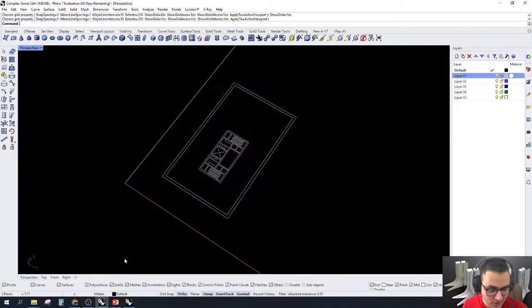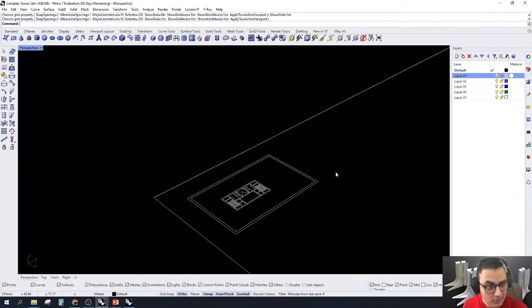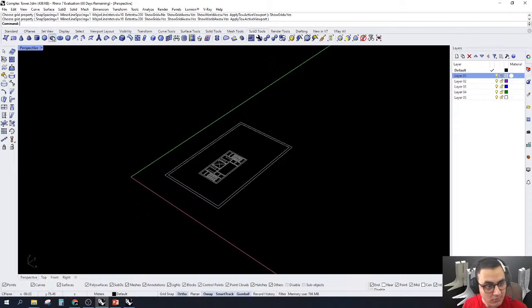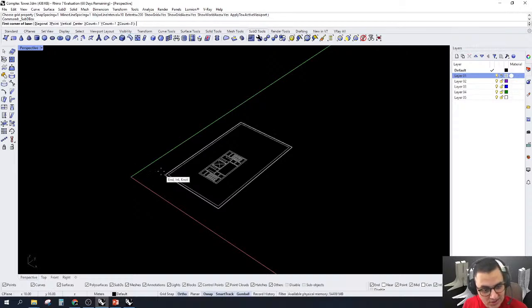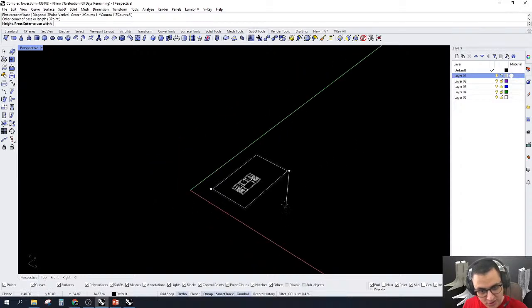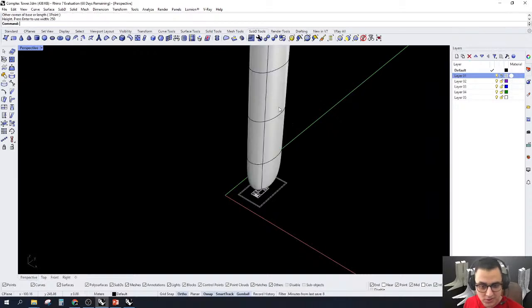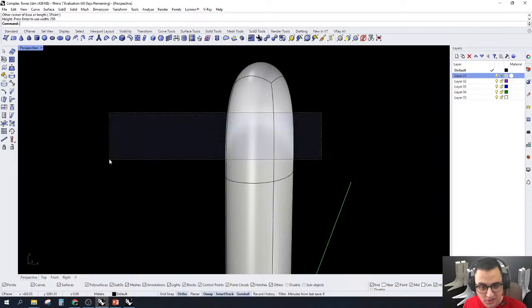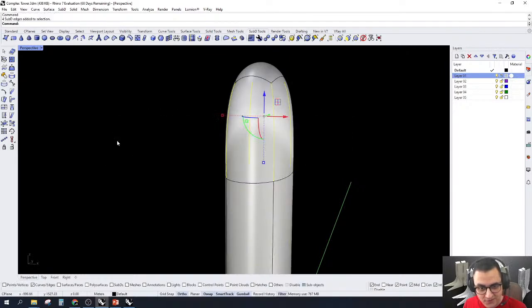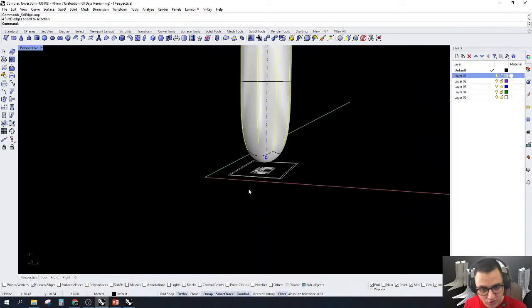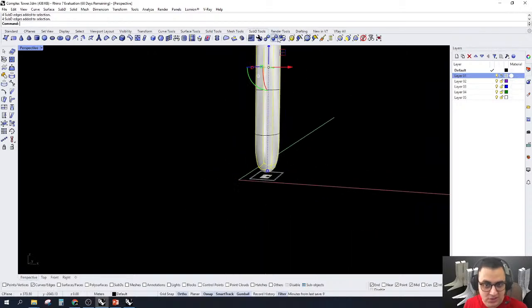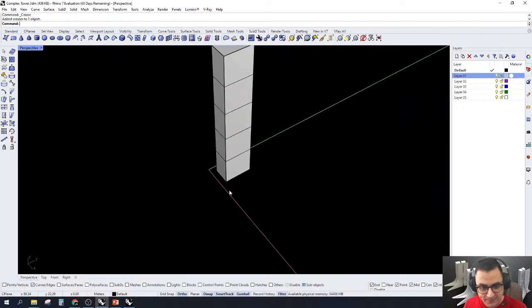And now let's start modeling. Let me create a SubD box from here to here, and with the height I will type 250, and I will get this one. I want these 4 curves, and simply I will select the edge loops, and after that I hit shift and pick the top and the bottom ones, and I will add a crease so it will look like a box.